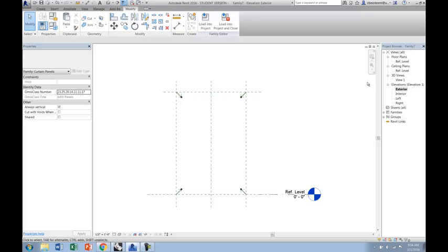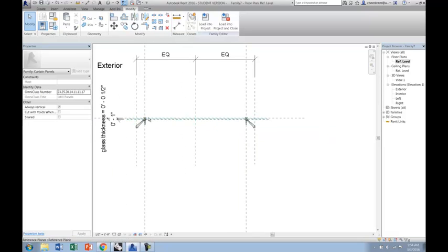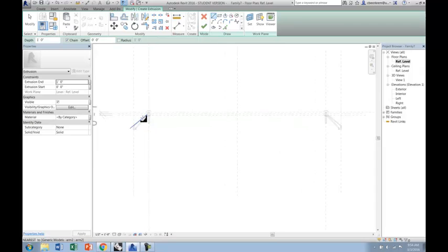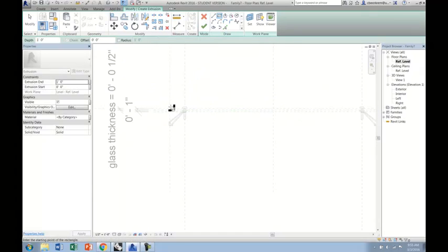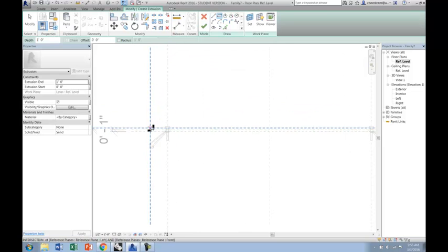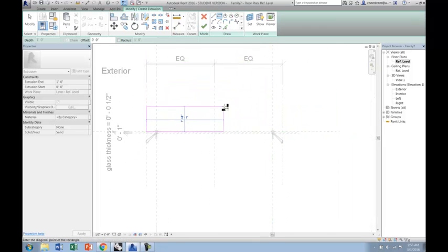So I'm going to come back into the floor plan view. And we're going to make a piece of glazing in the slot where it's going to be. So I'm just going to create an extrusion. And I'm going to draw our rectangle. Again, we're going to want this to go from the faces of the snapped elements here in the...